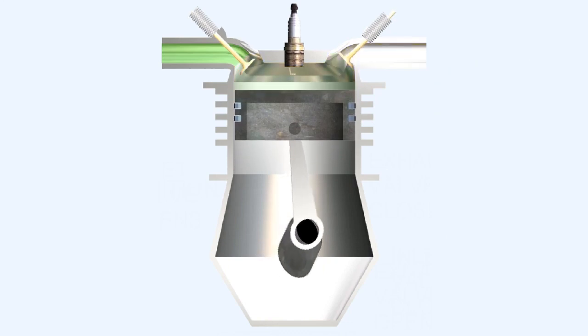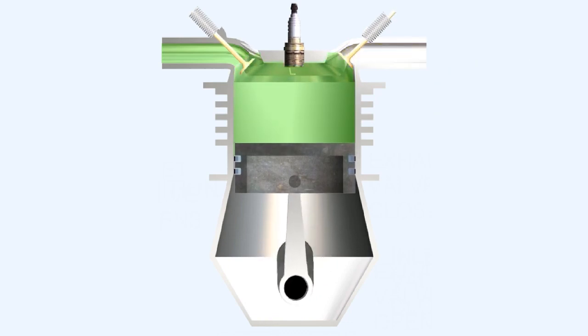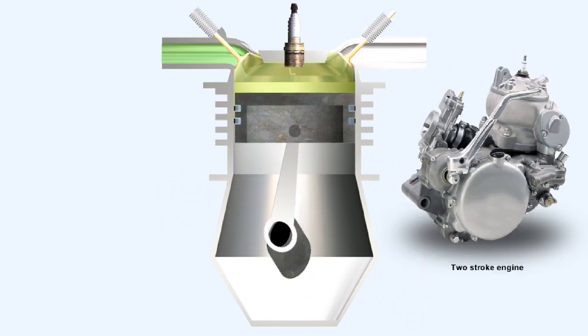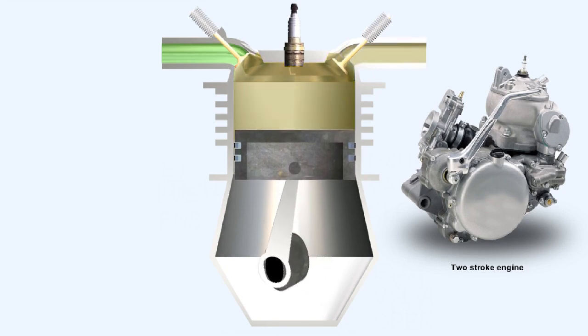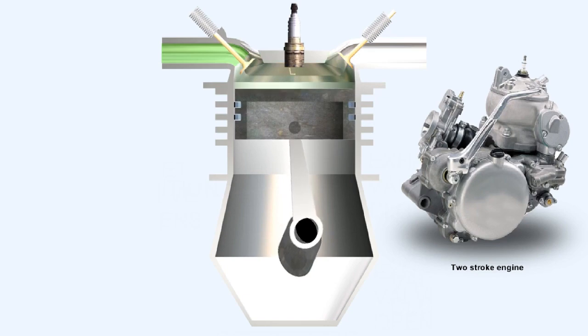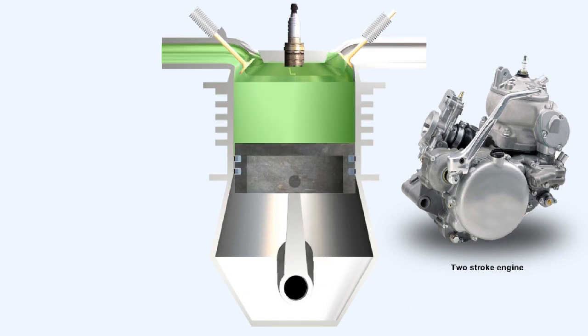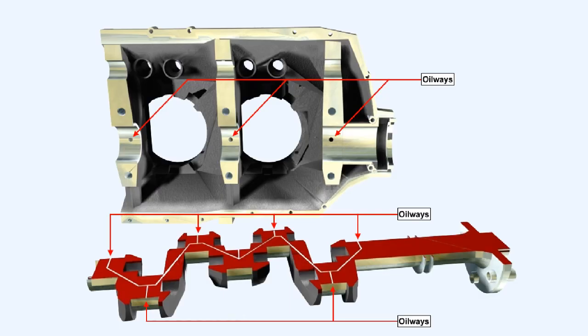There are 4 methods of lubricating the moving parts of an engine with oil. They are the petroil system, where lubricating oil is mixed with the fuel. This system is used mostly in small 2-stroke engines. The pressure system, which has a high-pressure oil pump incorporated in the design, which supplies oil under pressure for lubrication of the major components.